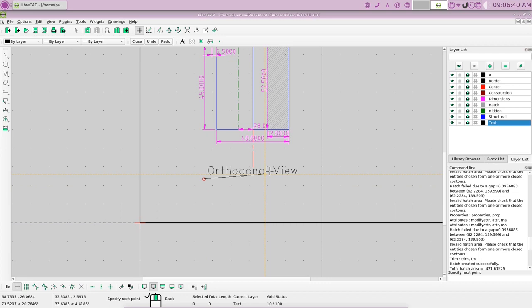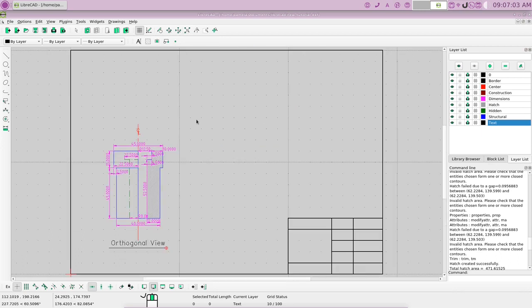Now, so that you don't get crooked here, let's restrain the horizontal. Again, make sure your yellow line is past the W there. Okay, and go ahead and click on that. Now right click to get off there, and there we have a view. Now go and zoom auto. There we are. Okay, there is our view.